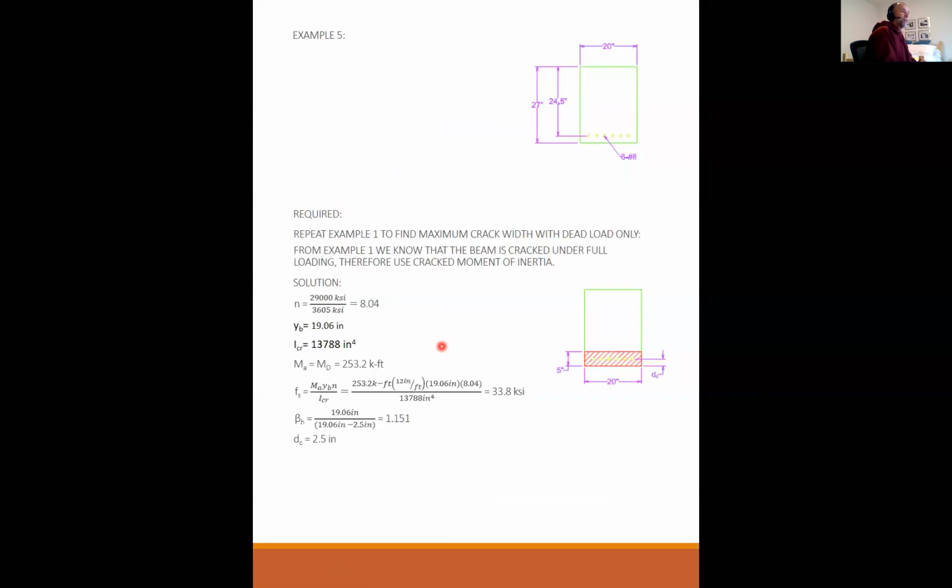Just as a comparison, when you start getting cracks that are like 17 to 25 thousandths, that's when it starts getting a little concerning. You look at a concrete beam and you see a crack that's 25 thousandths of an inch wide, you notice it. You're like, huh, what's going on with that? You start seeing cracks that are like maybe 1/8 of an inch wide, that's when you should really start being nervous about even being in the building. And I've seen cracks that are over 1/4 inch wide, but that was just before the beams failed in a testing situation.